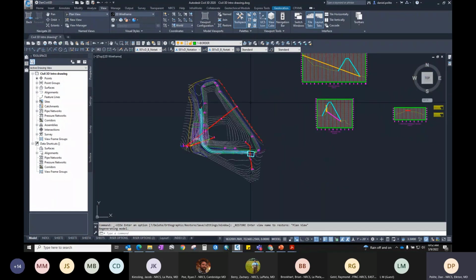Okay, now I want to change that, and I want to have my UCS showing that this is going to be my x-axis. So if I just went in there and drew an arbitrary polyline, there are a couple ways to do this. I could do it by object. I can follow the line. So I'll do follow by line first. I'll just type in UCS, and it'll ask me for the first object.